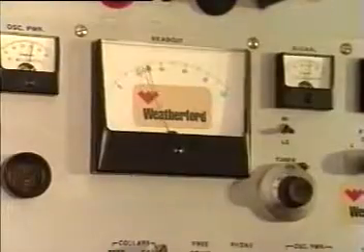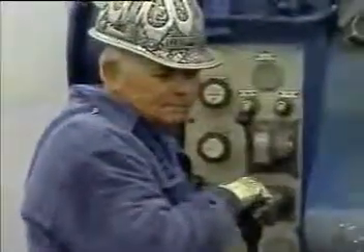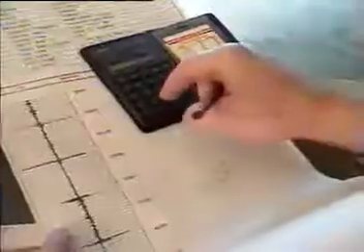The downhole free point reading is directly proportional to the amount of torque or stretch being applied to the string from the surface. After making a calculation to estimate the stuck point, experienced wireline operators begin taking readings slightly above the calculated stuck point. As the stuck point is approached, readings will decline until the detector is in the totally stuck section of the string, indicating no pipe movement. Through this method of data interpretation, a skilled wireline operator determines the free point precisely.